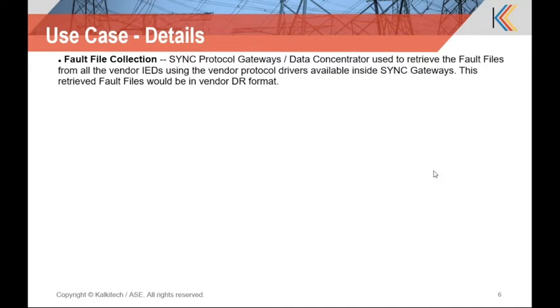The gateways or data concentrator retrieve the fault files from all the IEDs using the vendor protocol drivers available in the Sync 2000 itself, and this is retrieved in its own vendor disturbance record or fault file format.